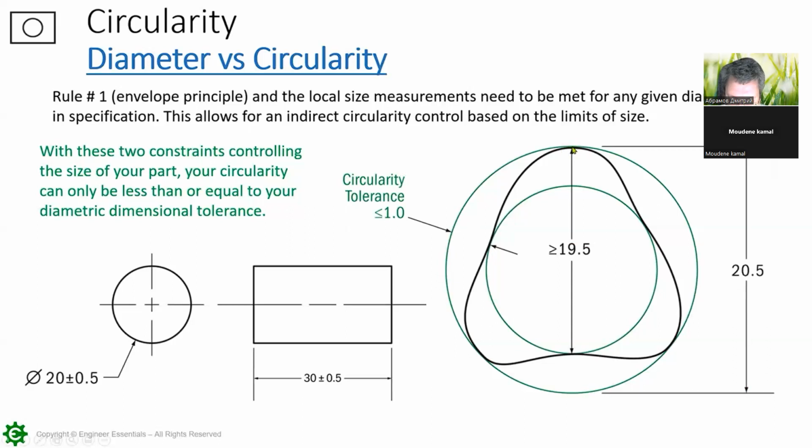Now, what this is showing is that surface on any given element is allowed to move within this tolerance zone. And again, that tolerance zone there is not LMC. That's a different one. LMC is the measurement, right? We always talk about when it comes to LMC like this on an external feature, and the same rule applies for internal.